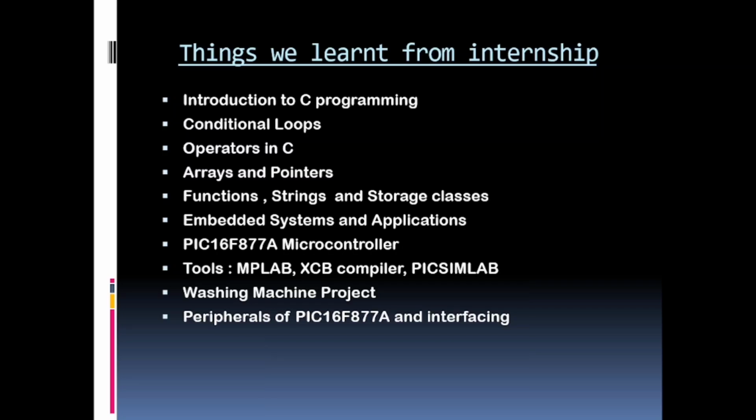Throughout this internship, we received both theoretical and practical exposure to embedded systems. We started with C programming, which is the foundation of embedded software development. We practiced working with loops, conditionals and operators, arrays and pointers, functions and strings, and also storage classes, which are important for managing memory efficiently in embedded code. We were introduced to embedded systems architecture, understanding how software interacts with hardware.